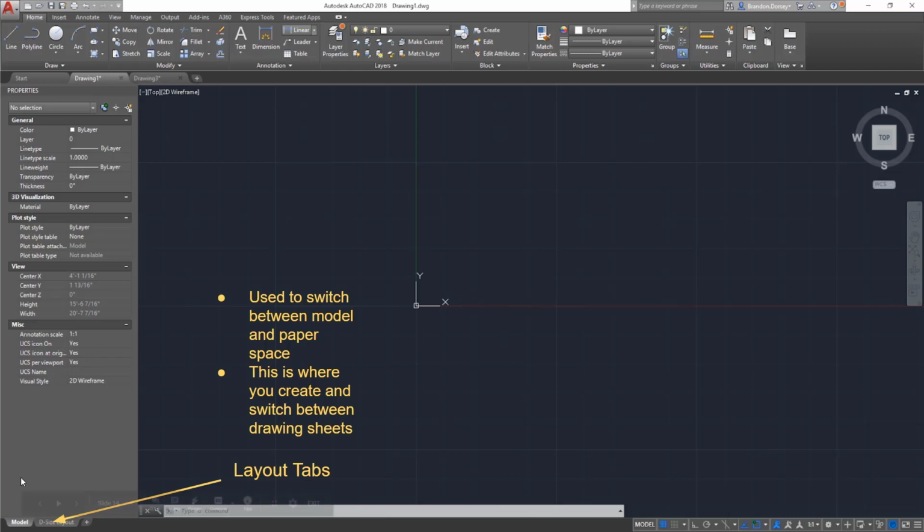Beside that, you can see this little tab right here. This one says D-size layout, but that is what's known as paper space, all right? So we'll talk about paper space later on when we're actually going through an actual drawing, but paper space is what you toggle to lay out drawings onto sheets, okay? It looks nothing at all like what you're seeing here.